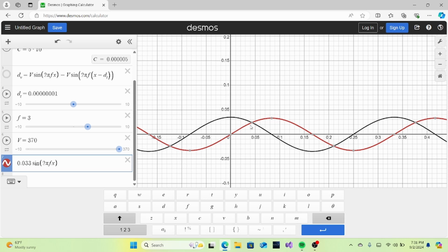So you notice here that if we were to take a derivative of this sine function, if we were to look at the slope of this red line at this dot at 0, it is pretty much the maximum that it can be. So that slope would look something like this. All right, but then what happens to the derivative as the voltage rises toward the peak? It gradually decreases, and eventually at this dot here, the peak, the derivative becomes 0. So you can see that here.